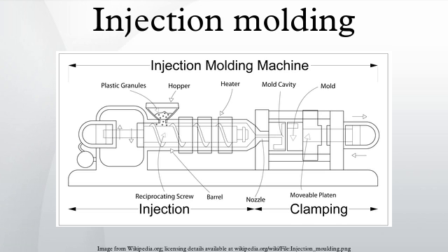These pins enter a slot in the slides and cause the slides to move backward when the moving half of the mold opens. The part is then ejected and the mold closes. The closing action of the mold causes the slides to move forward along the angle pins.